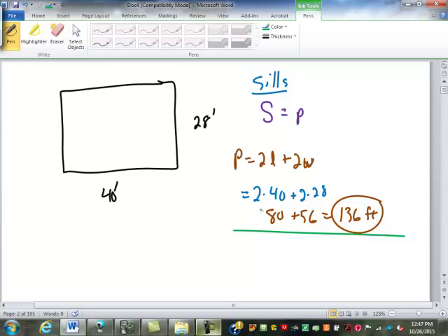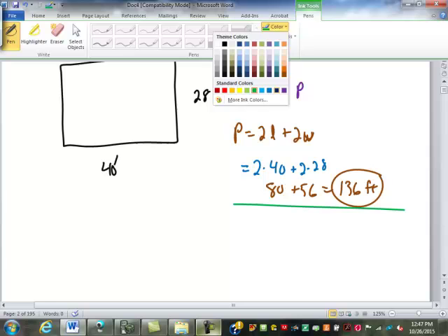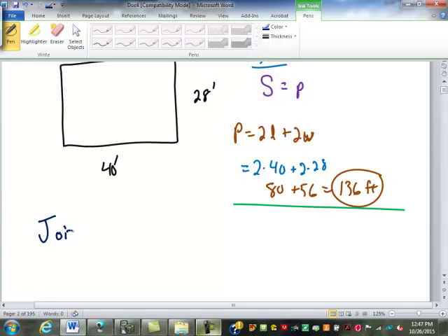What would be the next thing we would need? What sits on top of the sills? Not studs, but joists. If you're thinking this is a foundation, we have to have a floor before we can build walls. You're thinking a slab on grade where you're going right into the walls. If it was a slab on grade, your sills would have to be whatever thickness your walls are. You'd have a 2x6 sill instead of a 2x8. I've seen people use 2x8 or 2x10 sills depending on their walls. That's why I was thinking of the joists. Okay, that makes more sense.